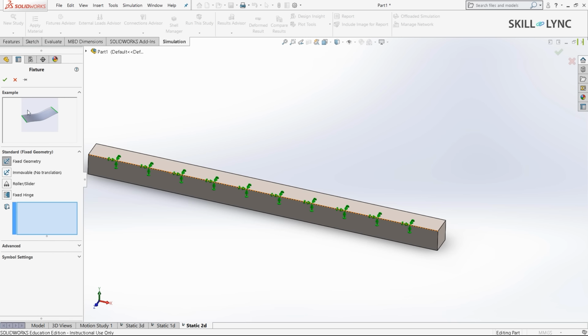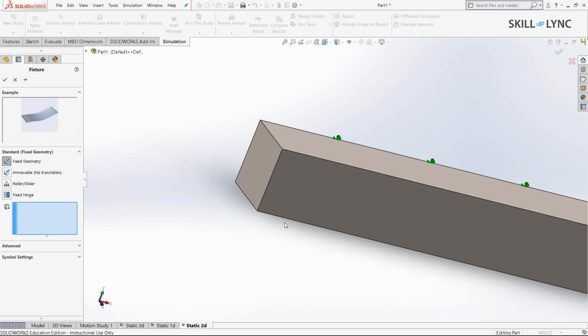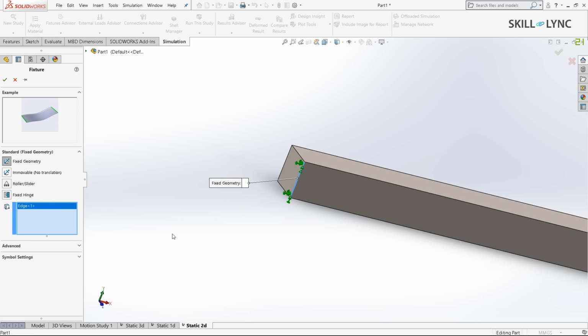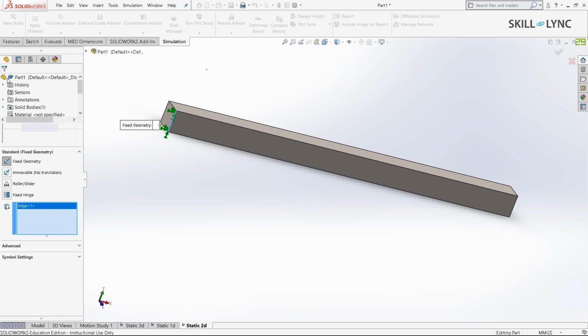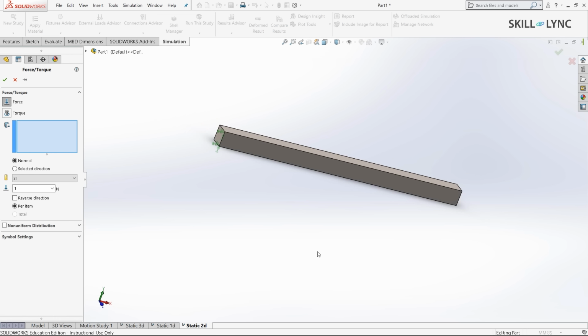In our previous one, we had a 3D element. We had a 3D cantilever beam which was moving up and down in the animation. Now we just have a simple sheet metal which is bending down and up. So this is to denote that this is taken as a shell element. So we're not going to give an entire face. We're just going to give this one edge because this edge is what we defined as a shell element. Select OK.